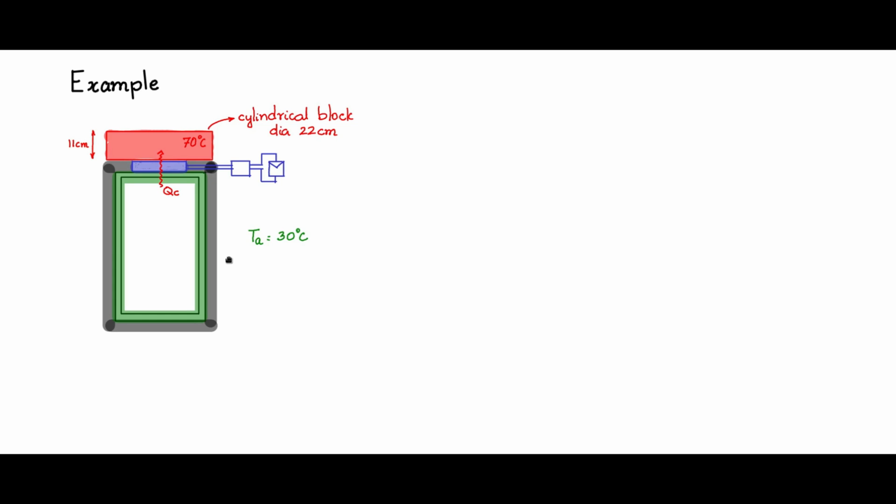Now let us analyze and understand it from the point of view of forced convection, because when you are putting QC amount of heat into the heat sink, that much heat plus the heat put in from the electrical side through the Peltier junction, the electrical power, both should be put out into the ambient. So let us calculate those values.